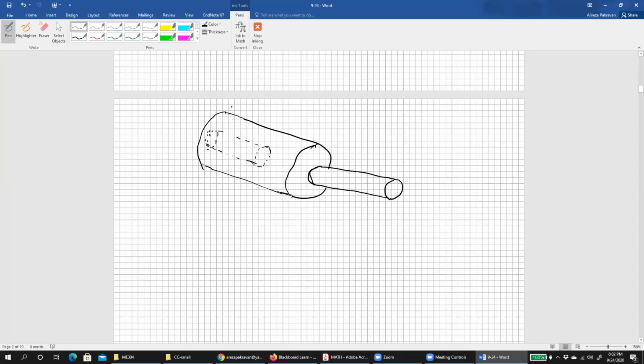Here we have a fixed support, so hopefully you can imagine. We have this shaft, and from this section we have hollow sections. Let's apply some torque here, 250 Newton meter, and here we have 2000 Newton meter. Okay, that's these two.